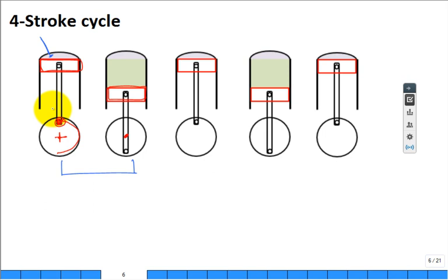It would draw it across the air filter, through the tortuous path of the ducting and the intake manifold, and there is some pressure drop that it has to draw it across that open intake valve. So yes, this is at a state of a vacuum during the majority of that intake stroke. Maybe as it starts, it's still not at a vacuum. It has to pull down enough to make it a vacuum. But that's our intake stroke.